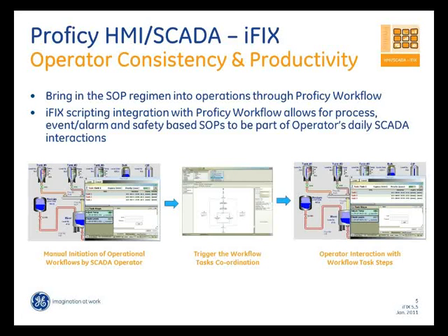All of these today, up until say iFIX 5.0, or even based on the preference of the customer, a lot of it is scripted in VBA, or there are external programs that run and do these checks and balances. The Proficy Workflow provides a graphical, flowchart-like interface where you can use that more as an SOP engine tied to the iFIX SCADA.